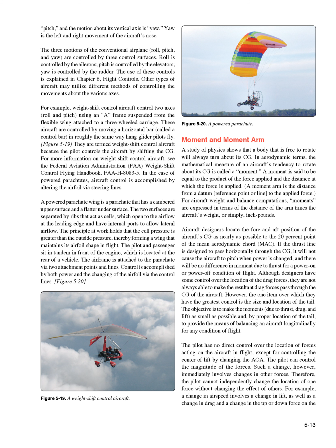For aircraft weight and balance computations, moments are expressed in terms of the distance of the arm times the aircraft's weight, or simply inch-pounds. Aircraft designers locate the fore and aft position of the aircraft's CG as nearly as possible to the 20 percent point of the mean aerodynamic chord, MAC. If the thrust line is designed to pass horizontally through the CG, it will not cause the aircraft to pitch when power is changed, and there will be no difference in moment due to thrust for a power on or power off condition of flight.